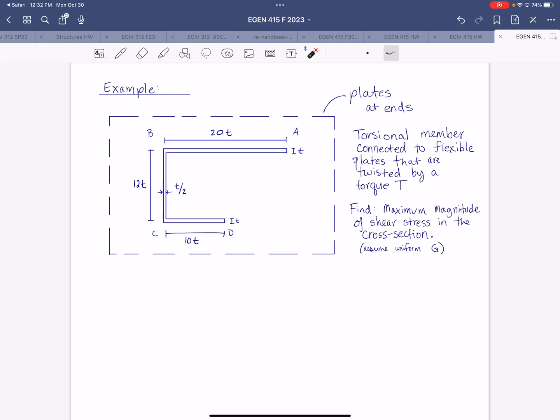It's really because the shear will flow through the section in this direction. If you're applying a torque in that direction, that shear flow will be through here. So that length is what's providing that continuous path for shear. You don't really get that in the thickness direction.